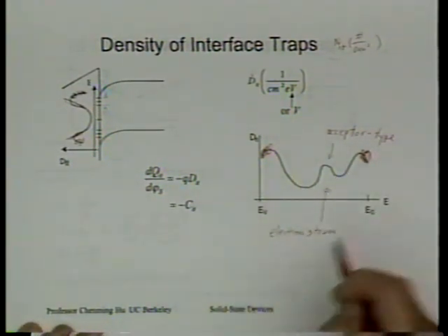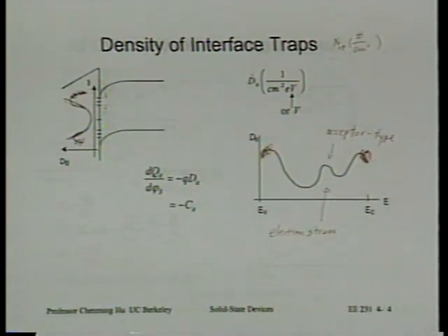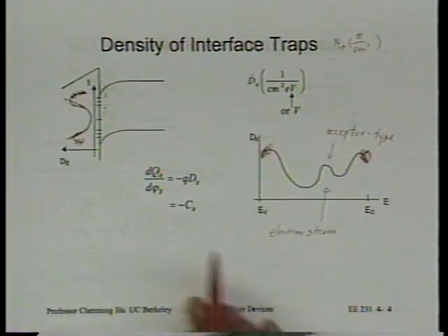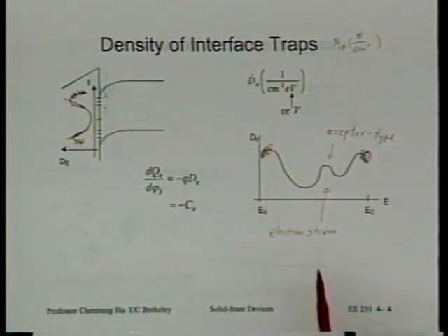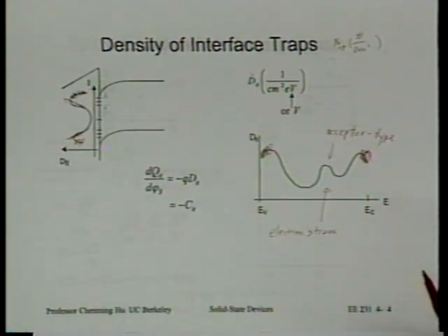So it's true. Devices that have been electrically stressed tend to show you positive charge in the MOS system, all right? So for PMOS and NMOS, VT will change in different manners. One will become harder to turn on, another will become easier to turn on. And so that's why we need to understand these details about the behavior of the traps. All right? Okay, good. All right, next.